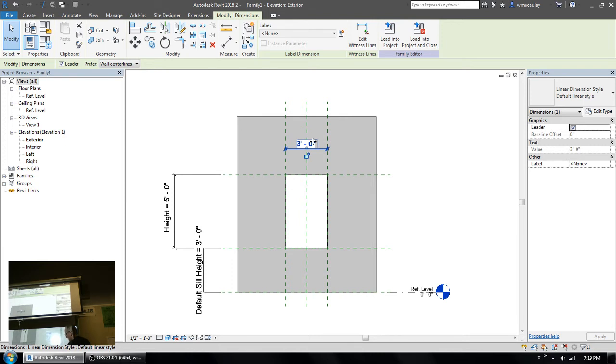The door that's going in this opening, we'll want to hide the 3D door in plan. Instead, we're going to show 2D graphics to show the door in the open position as per architectural practice. So 2D stuff shows in plan, 3D stuff not showing in plan. So Revit has the control over all of that stuff, so we can make those choices.